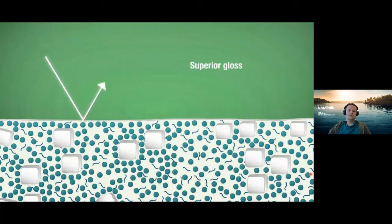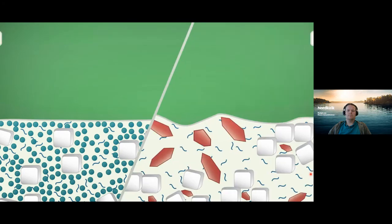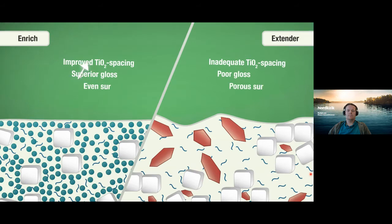Superior gloss improvement is achieved when the ultrafine Enrich particles evenly fill the paint surface, intensifying its light reflection. Despite only partially replacing the titanium dioxide and binders, Enrich succeeds in maintaining the desired level of hiding power. The transmitting light path reaches further into the gaps of the mixture, dimming a contrasting colored substrate. In contrast, in the presence of large extender particles, the optically coarse particles deteriorate the light scattering performance due to inefficient spacing.